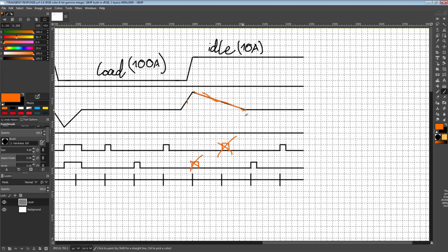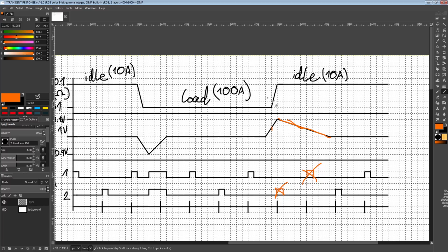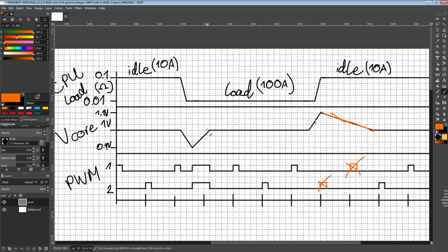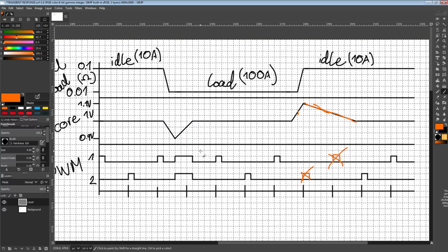And then eventually our voltage level drops to appropriate levels, and we can go right back to steady state operation where you have your regularly spaced 10% PWM pulses. And that right there is load release overshoot, right? Like this right here is a load release transient, and this is overshoot. And overshoot, again, is relative to the voltage you're aiming for. So here we're always aiming for 1 volt. So we have 100 millivolts of overshoot, we have 100 millivolts of undershoot, and so we have a min and max voltage: target voltage 1 volt, min voltage 0.9, max voltage 1.1 volts.